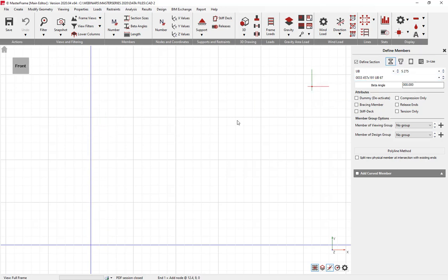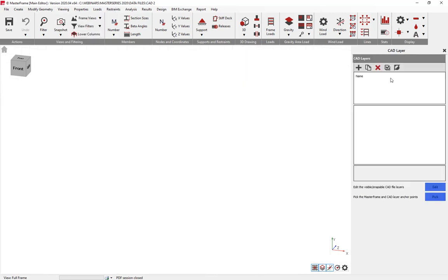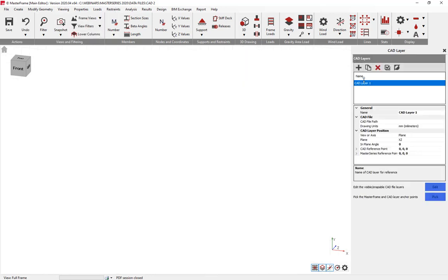And this demonstrates to us basically how the snap area works, in that we have always had, for quite some time, the ability to work with snap grids and to work with snapping on structures and things like that. But this snap area we thought would be really, really good if we could augment it with an additional layer of CAD drawing entities, and that's exactly what the CAD layer does. So we find CAD layers by going to the View CAD Layer, and the CAD layer interface simply allows us to add in a new CAD layer setting.